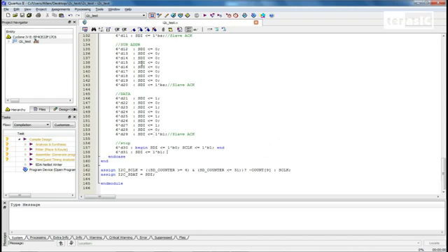So our SDI register will go feed into our pin on the EEPROM, which is the I2C SDAT. We've assigned it here. And our SCL clock over here will feed into our EEPROM pin, given the condition that the SD counter is greater or equal to 4 or less than or equal to 31. So let's see this in action in Signal Tap 2.